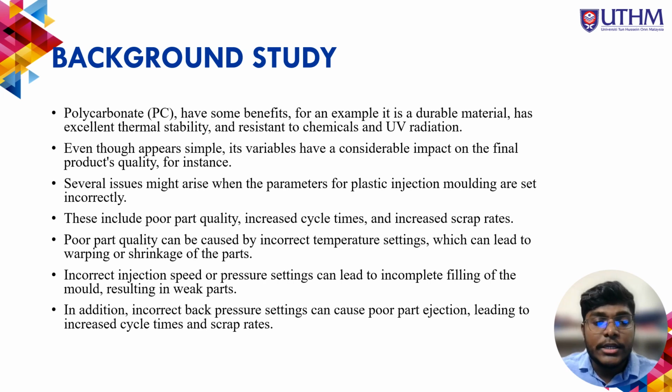Poor part quality can be caused by incorrect temperature setting, which can lead to warping or shrinkage of the parts. Incorrect injection speed or pressure setting can lead to incomplete filling of the mold, resulting in weak parts. In addition, incorrect back pressure setting can cause poor part ejection, leading to increased cycle time and scrap rates.